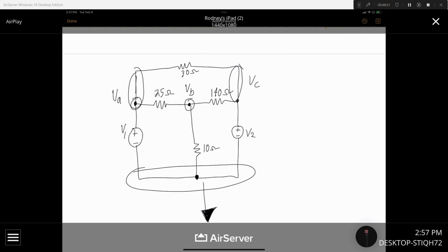Now, part B is asking: when a branch of a circuit that connects two essential nodes contains only a voltage source, a special case exists. As you will see in part C, how many branches in this circuit contain two essential nodes and only a voltage source? From VA to V1, these two here, we have this case and this case here. So there's a total of 2.